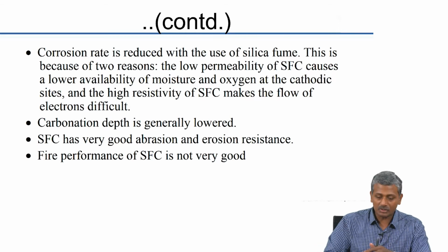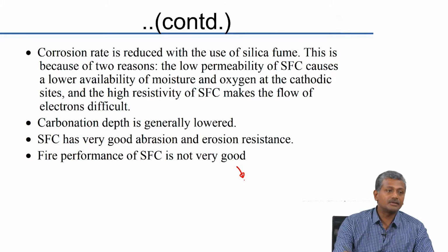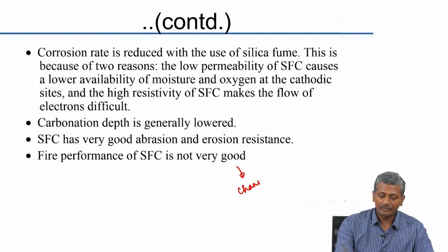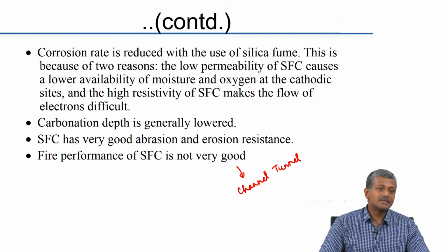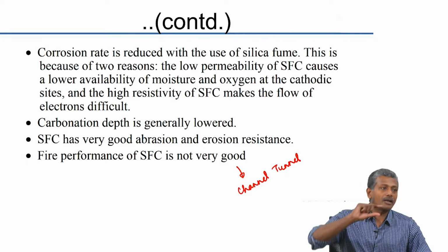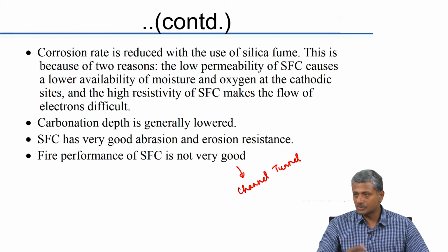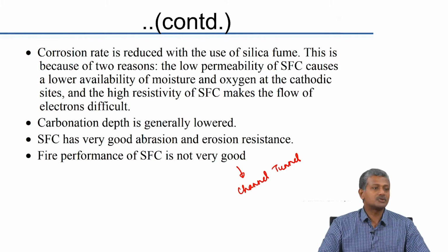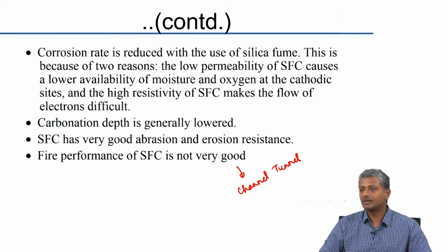So, this was found when the tunnel linings in the Channel Tunnel between England and France. Okay, you know that there is a Channel Tunnel which links England and France by road, and that goes right under the English Channel, right. And in this Channel Tunnel, there was a petrol tanker that actually caught fire inside. So, there was very high level of heat inside, and the tunnel linings which were made with high performance silica fume concrete collapsed almost instantly. That is because the water inside started converting to steam, and it causes the concrete to burst out. So, all the linings were simply destroyed.